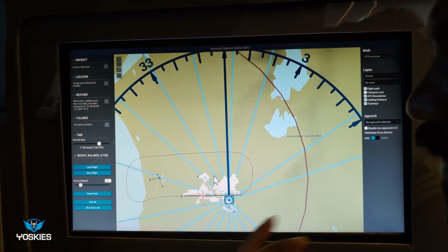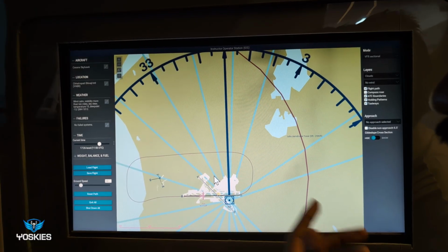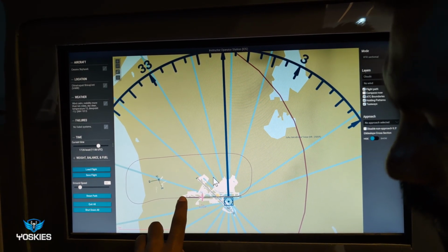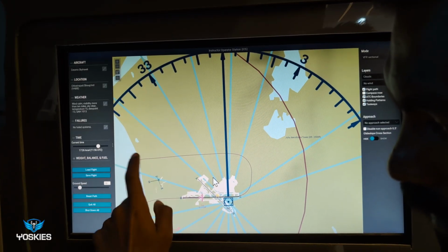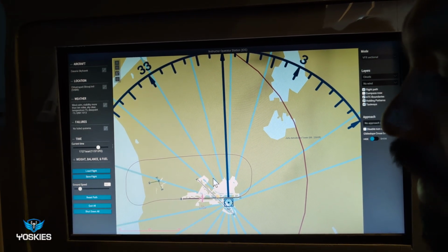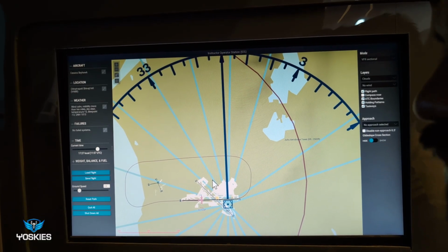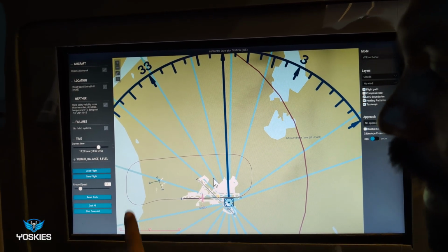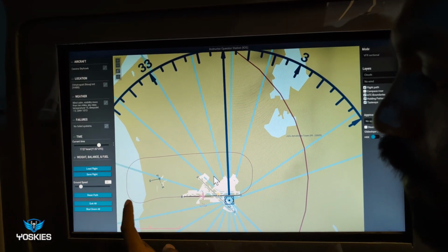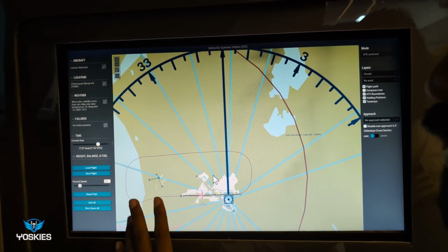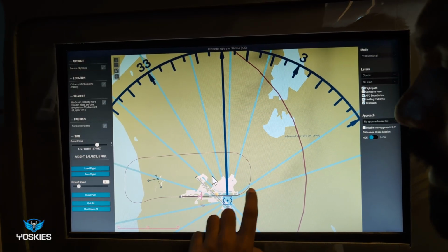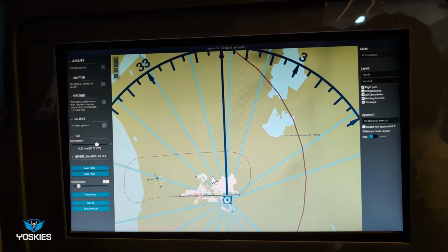That means you will bring your power back to 17 to 1800 RPM and start your descent. So again, when you make 45-degree angle with these numbers, is when you want to start your turn to the base. On base, you will add flaps 20 and maintain the speed of somewhere around 70 to 75. And then you will turn finals, and this is your final leg. So basically on finals you will add full flaps and maintain your final approach speed, which is 65 knots and land. So this is how the circuit pattern looks.